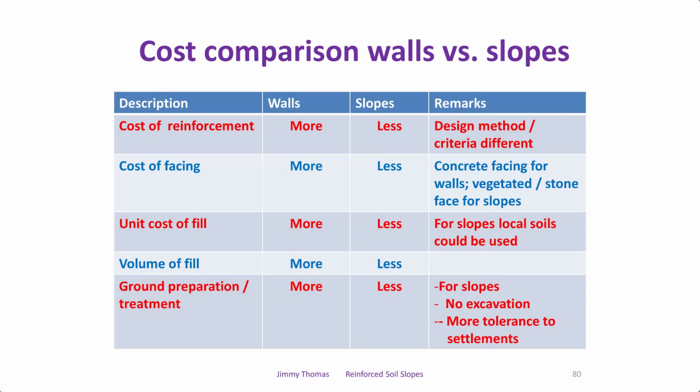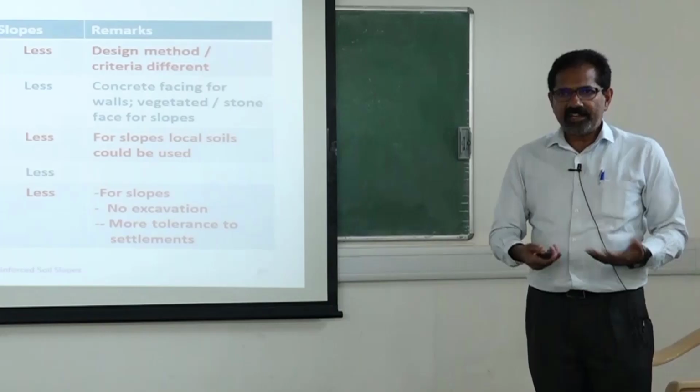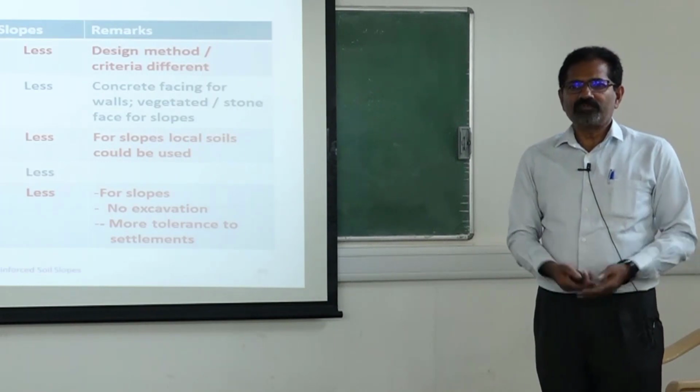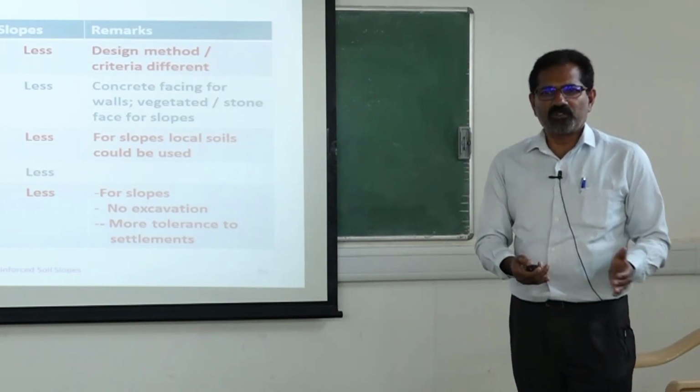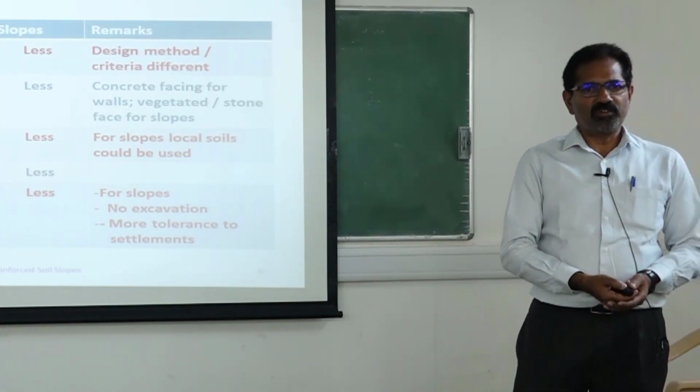Then ground preparation, because bearing capacity and settlement requirements for walls are more stringent compared to slopes, and there is no excavation like that. So even that cost will be less. So overall, we can expect the reinforced soil slope to be a much more economical solution.